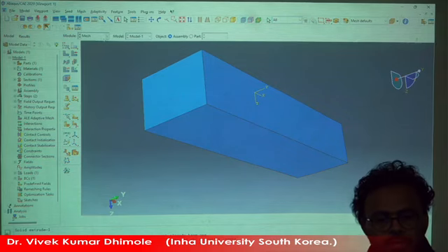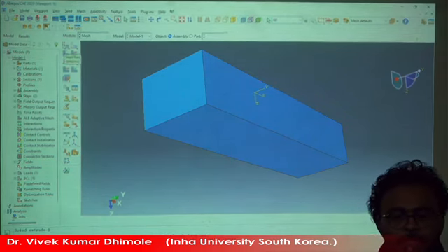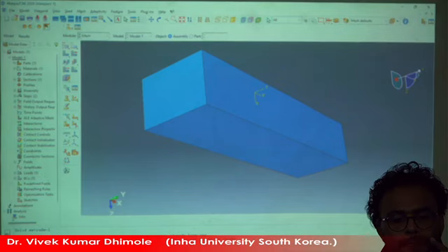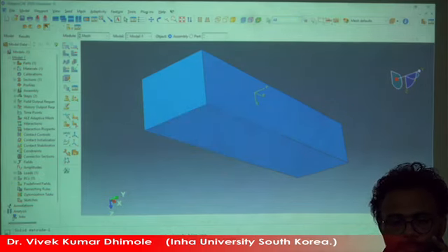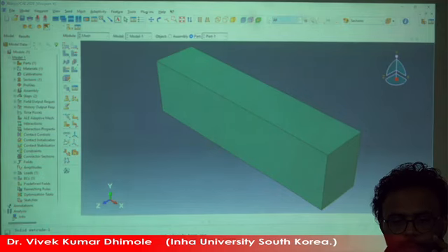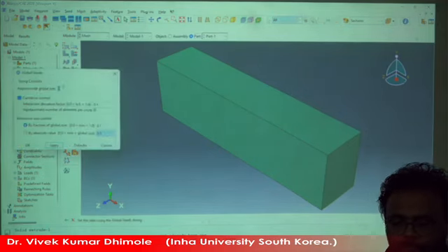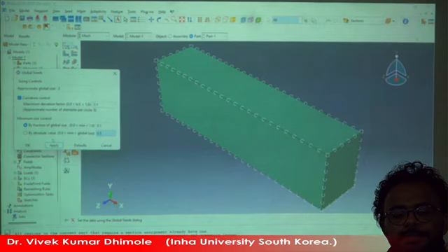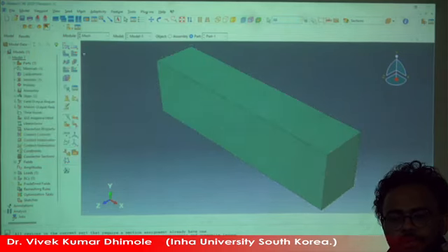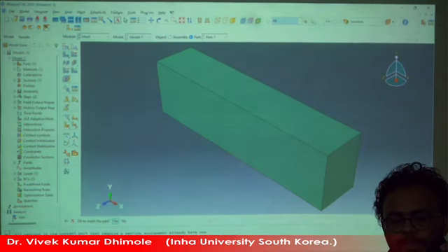Okay, now meshing, we have a seeding option, see here. This decides the nodes and elements, and we can decide different kinds of element systems. Node-dependent instances cannot be assigned here, we have to make the part mesh, right? So let's see the mesh. They are making an approximate global size of 5, so we just make it 2, something like that, apply, this size is defined, right? Node is defined means all nodes are defined. Then we can see the meshing and we can generate the part mesh, right?